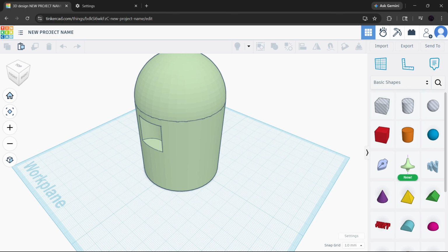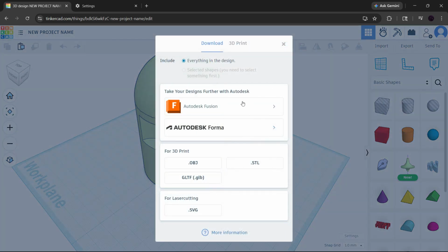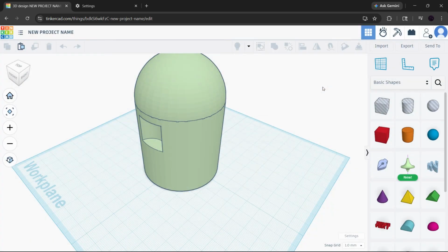There's one more important fix that often solves confusing STL import errors. Re-export the file as a binary STL. Sometimes an STL file has header problems or gets saved in a way that Tinkercad doesn't like, especially if it's ASCII format. Open the file in a 3D viewer or editor, then choose Save As or Export, and make sure you save it as a binary STL. This refreshes the file structure and can fix issues like invalid header or corrupted file errors.